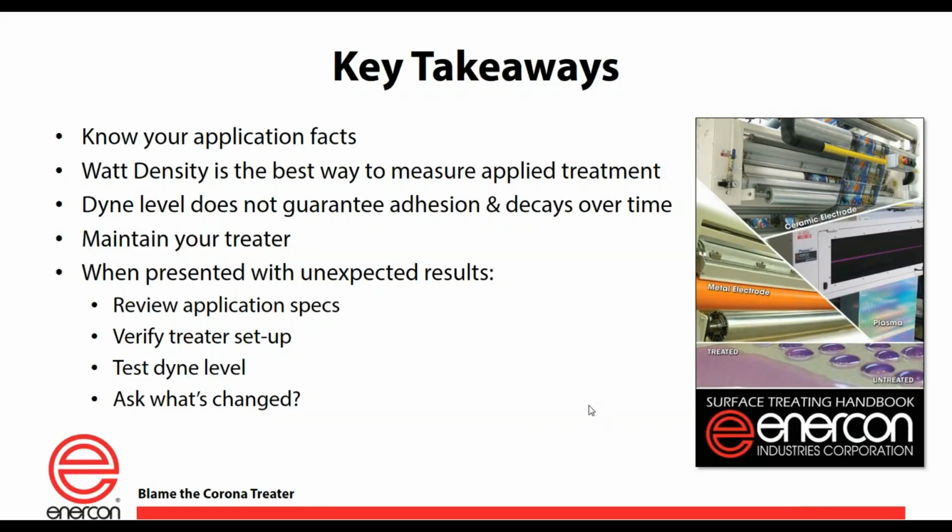Absolutely, Mark. Well, I think the number one thing we all can get from this little podcast play here is know your facts, know your application facts, understand what's happening in front of you. Make sure you understand things like what condition is the film in, what dyne level is it at, what am I doing with this particular product. Also, watt density is the best way to measure applied treatment, right? Not necessarily dynes. Think about the power of this, folks.